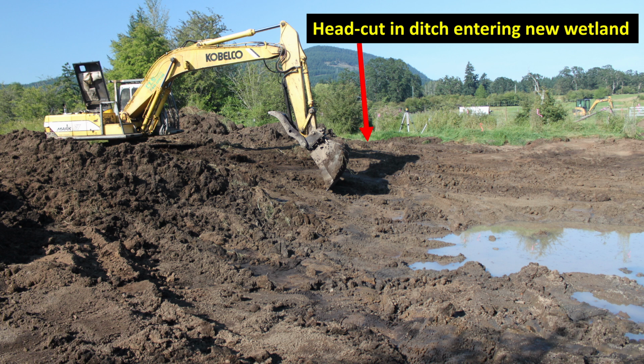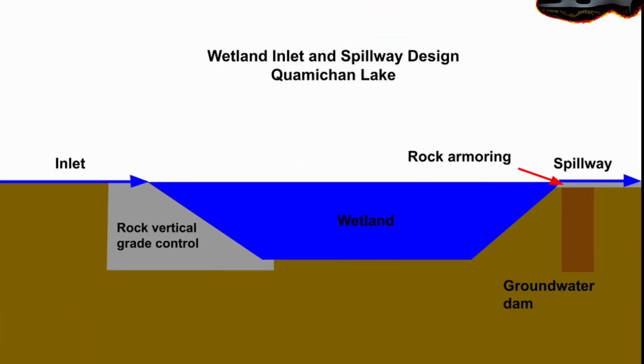I was concerned that digging the wetlands would cause additional headcuts to form and that the soil washing downstream would quickly fill the new wetlands. To control erosion, we constructed a buried vertical grade control structure across the ditch, and this was done where water entered each wetland, and then we sloped and armored the outlet or the spillway for each wetland. We also built a groundwater dam across the ditch at the lower edge of each wetland being built.